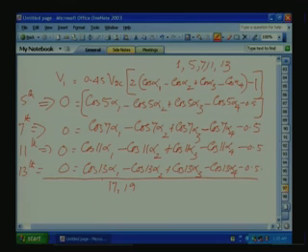Here, as I told before, for 3-phase applications, sine triangle PWM is the best approach, wherein we have a fixed triangle frequency and whatever amplitude of fundamental V1 we require, with that frequency we generate the corresponding sinusoidal waveform with 120 degree phase shift and do the appropriate switching.